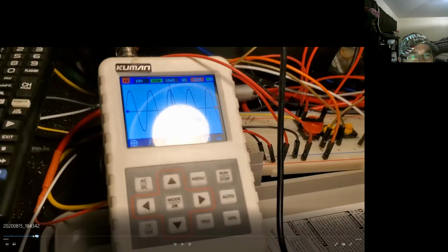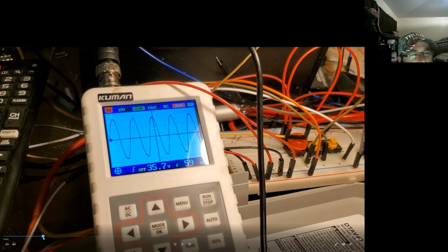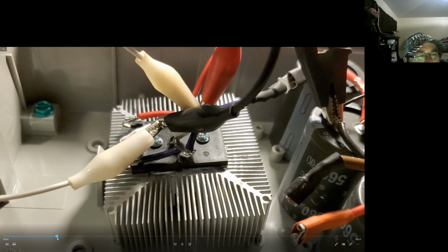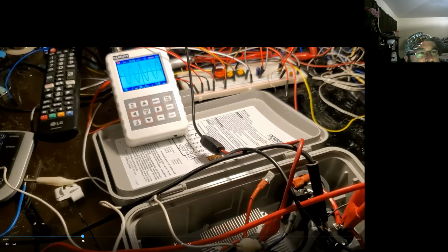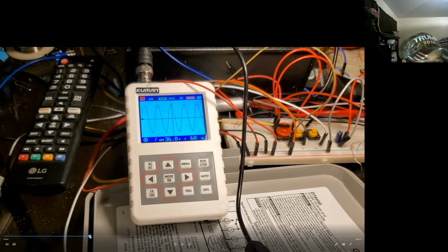So I have these 2. I put them with heatsink paste on this old computer CPU cooler, and I just have it temporarily wired because I wanted to show you guys what it looked like hooked up in different methods. When you first plug it in, you get this nice AC sine wave. Then I was moving it through there and showed you guys how the diodes work. There's a nice good picture of it too. It's low voltage. I'm coming out of a low voltage transformer, and I was using a 230 volt tap or a 480 tap, which gives 120, just to make it a nice low voltage to not fry anything here.